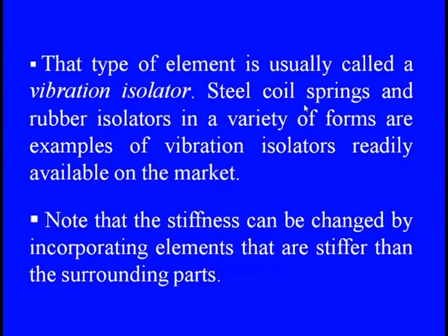As we discussed already, it can be a steel coil in terms of a spring. Sometimes they are rubber isolators. The spring coil provides service through stiffness variation. The rubber isolators provide service through their damping feature, or else sometimes the masses, which straightaway provide, through their weight, the suppression of the isolation amplitude.